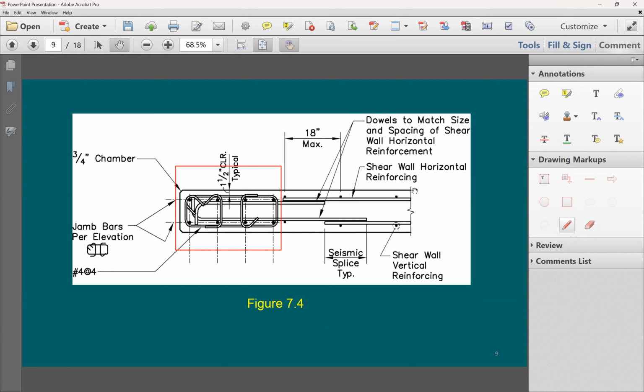Your shear factor for beams is going to be equal to 2, right? So the shear factor equals 2 for beams, when you have a tall shear wall. When you have a short shear wall, your shear factor is going to be growing up. It can reach all the way to 3. How about if the aspect ratio of the wall is in between? Code says you can do interpolation. So we're going to go to the next slide just to show this factor, then come back here.